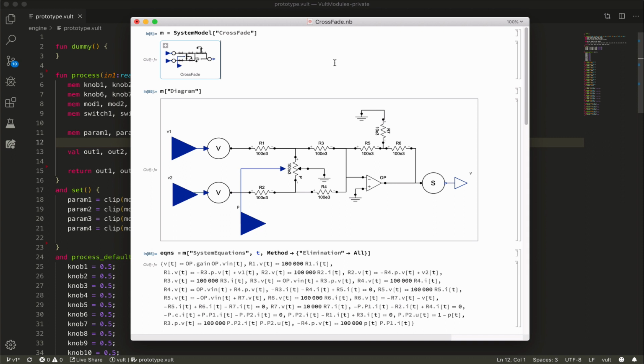Okay, so one thing that I need to correct before continuing, it was in my crossfader model. I forgot that I needed to add a gain compensation stage. So the curves that we're having had a very low gain, and this crossfader circuit needs this operational amplifier in order to return the signal to an appropriate level.